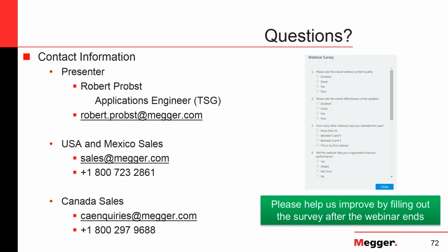Yeah, I know from field experience that certain utilities are testing important circuits every year, or even the manufacturer requires it for special applications, or it's DC, so primary injection also applies to DC. And sometimes these breakers are tested every year. Sometimes the time is extended, as John said. But that is to be decided by the user. You have to come up as a user with the test procedure, and you have to validate and pretty much defend that procedure, and you have to justify it.